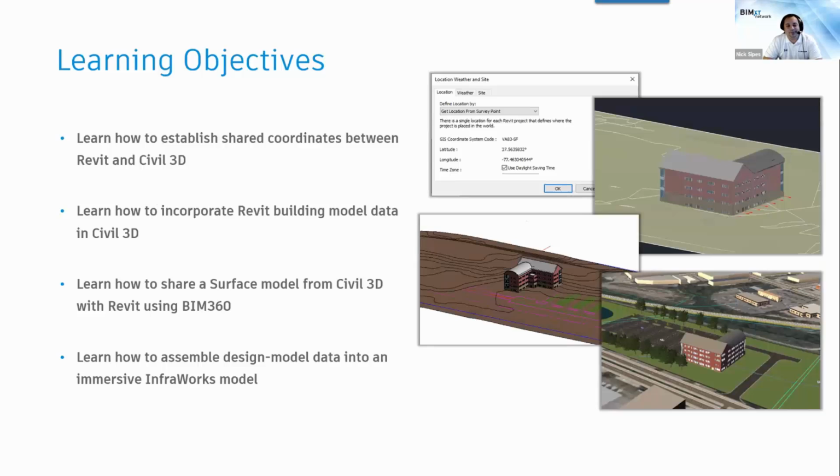It's software designed to handle not only a building being located in one place, but theoretically you could put that same building in several locations, which is really confusing to most people. The other thing people say is that Revit doesn't understand GIS coordinates, which is mostly true. It doesn't, not without the help of Civil 3D.